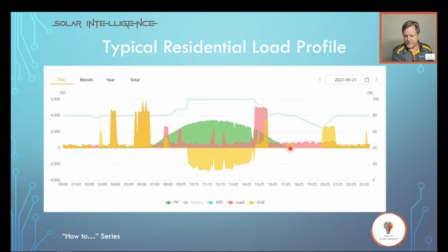As you can see, there's a bit of use of the grid, and then here is no grid for that period. So that's obviously load shedding. So during this period, the battery carried the load. Remember the fuel tank? The battery was used to supply the load. Here, Eskom came back on again, and now you can see there's more consumption from Eskom than what the load is. Obviously, that excess that we're using from Eskom now is to recharge the battery to get the battery to 100%. Once the battery is at 100%, Eskom drops down, and then Eskom is just enough to maintain the load to keep the house, the lights, going. Does that make sense? Okay, so what did we say?